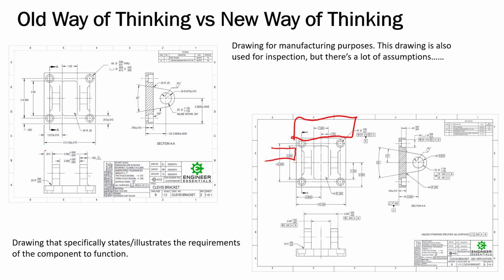And they can take this, it's called a work fixture offset, and shift this if they need to. This would be the one for X. This one over here, which would be this front face, this would be the one for Y. They can shift those any way they need to, comp those, if you will, in order to get this part to sit where it needs to, in order to put in the through holes if they wanted to at this point. It's sitting on A, so they could put in the through holes and the counterbores together. But like I said, they get to choose how to do this any way they want.